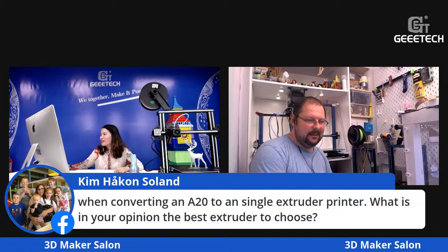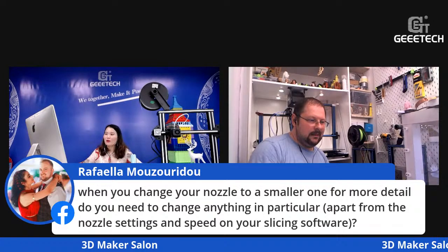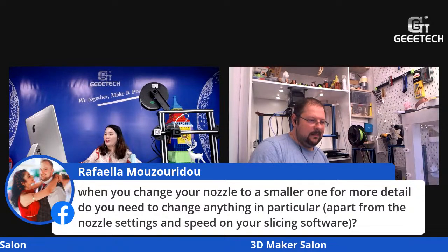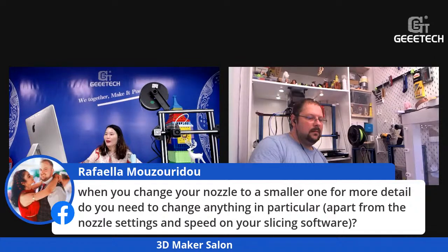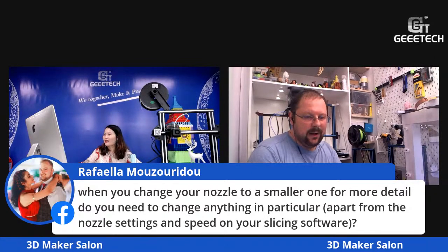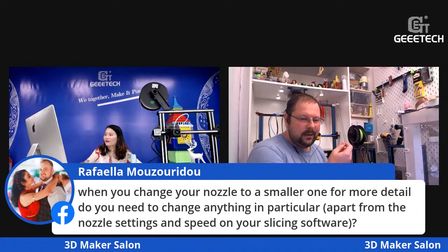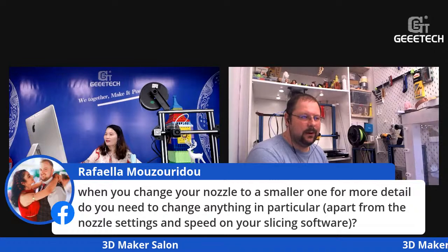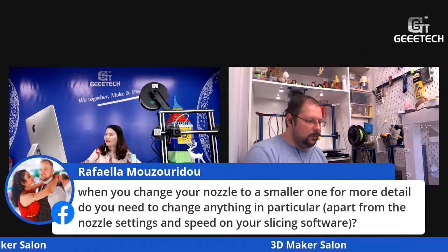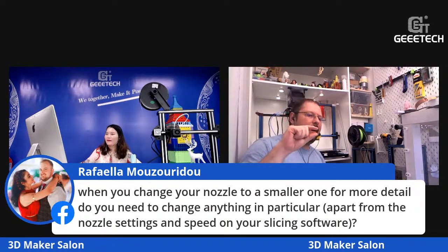Okay, we got a question from Rafaela. When you change your nozzle to a smaller one for more detail, do you need to change anything in particular apart from the nozzle setting and speed in your slicing software? No, Rafaela. If you change the nozzle, you change only the nozzle on the printer, and you change the nozzle size in your slicing software. Maybe in your slicing software you must also adjust the extrusion width of the nozzle and the layer height.